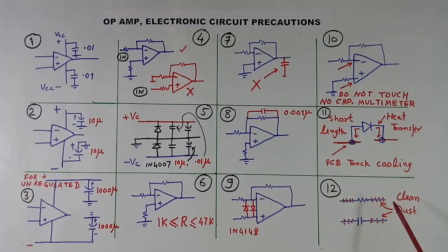This will help in improved contact between this terminal and the board, whether you are using breadboard or PCB. In both cases, this should be cleaned on both sides. Even if you are using a new component, you must still clean it, because you might have seen they put resistors and capacitors in a pack that uses some kind of gum to keep so many resistors together in a strip.